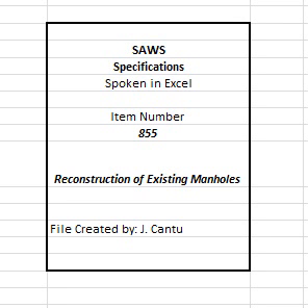4. The contractor is hereby instructed to conduct either of the two identified tests in the following manner. A. Hydrostatic testing shall be conducted by utilizing approved plugs to seal all influent and effluent pipes in the manhole and filling the manhole to the top of the cone with water. 1. Additional water may be added over a 24-hour period to compensate for absorption and evaporation losses. 2. At the conclusion of the 24-hour saturation period, the manhole shall be filled to the top and observed.